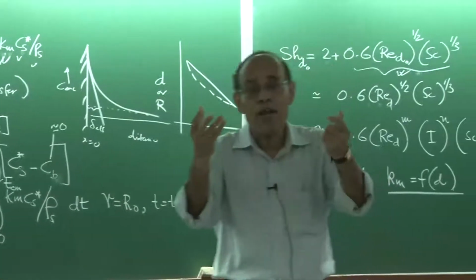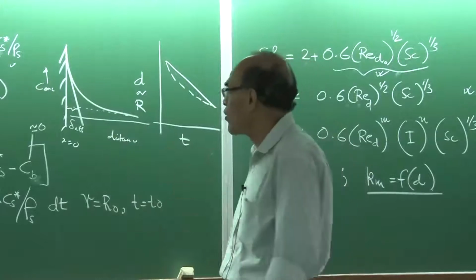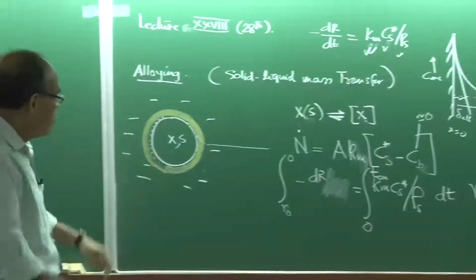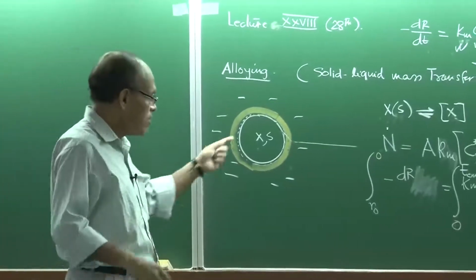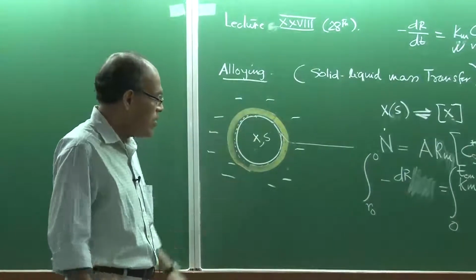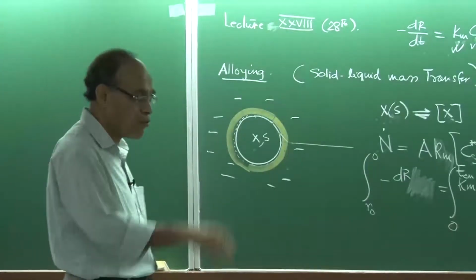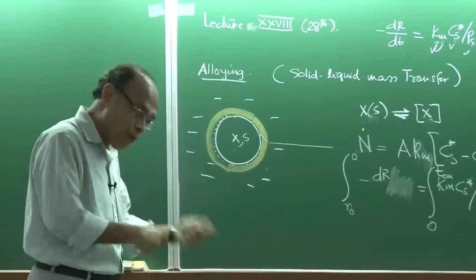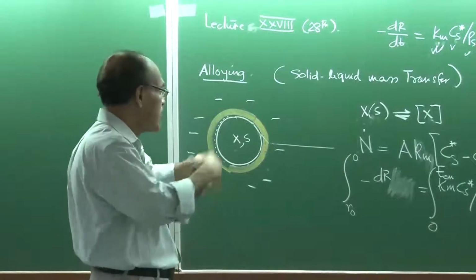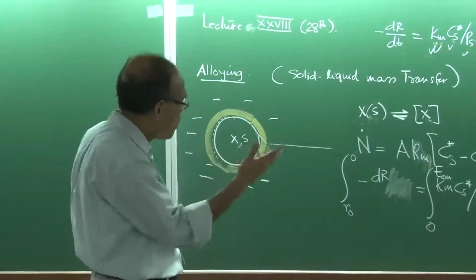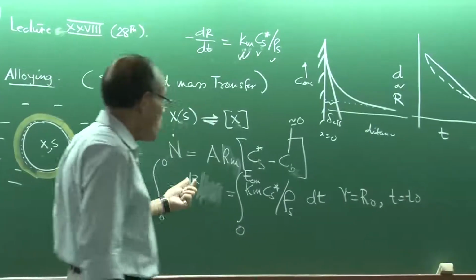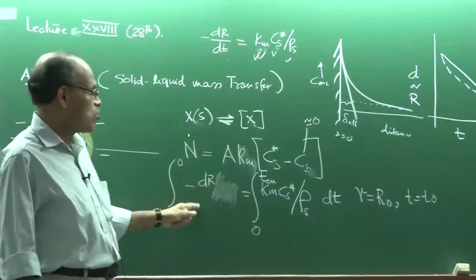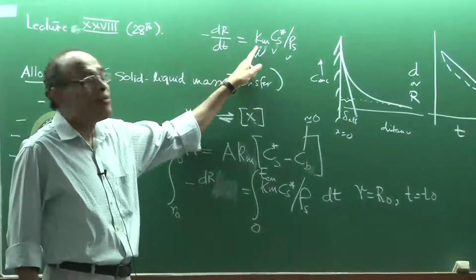Naphthalene is getting evaporated. So it is a problem associated with, looked at from the same standpoint, a diffusion process, but nonetheless it is an analogous scenario as considered in this particular problem itself. You can consider air to be a fluid phase, and this naphthalene vapor, of course, is not dissolving in air, but it is nonetheless getting evaporated, and there is a reduction in diameter. So the phenomenon is basically identical. Therefore, it is possible to calculate the initial rate of dissolution only by substituting Km is equal to half.